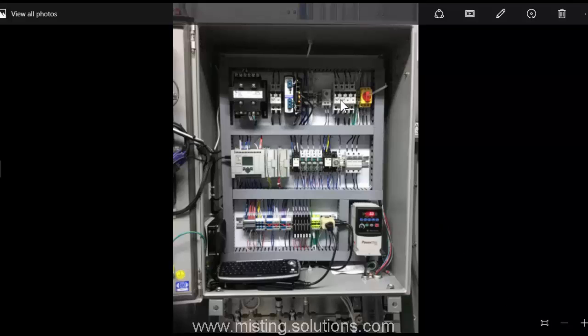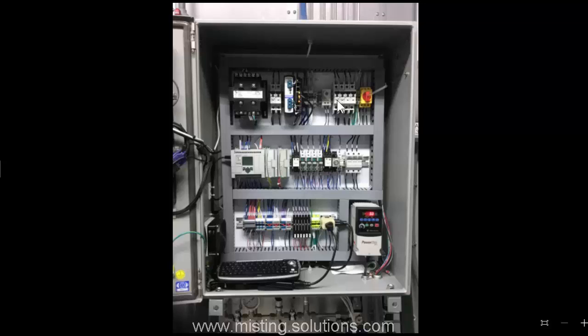First 4 here is the main circuit breaker. In fact, it's the first 3 to the right. The one to the left side is just a single pole circuit breaker that provides the 120 volts to this receptacle right here for the power supplies for the PC and for the display. So it is not tied to these other 3, even though it is next to it. These other 3 are ganged together for a 3-phase circuit breaker. By the way, that's 208 volts, 3-phase, 20 amps with a neutral. And so that breaker to the left of it is just a single pole, and it's actually at 8 amps, providing power to this receptacle.